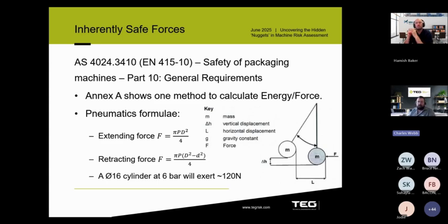But one of the big ones for me as a designer, this was really valuable for me, because when I work with pneumatics, I need to know, well, I can now calculate what forces my cylinders are going to exert on a person. So I can go back to my force calculations, force as a result of pressure and area, for extending and retracting.